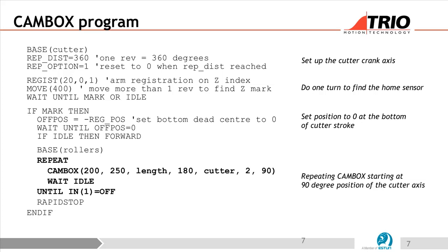And sometimes if people want to do more complex coordinated moves based on torque points, you can actually run 2 or 3 or 4 cam boxes all following one virtual master. So they would all follow together along one virtual master, and then everything will work repeatedly in a coordinated way. So you can repeat the same thing or move something slightly, you know.